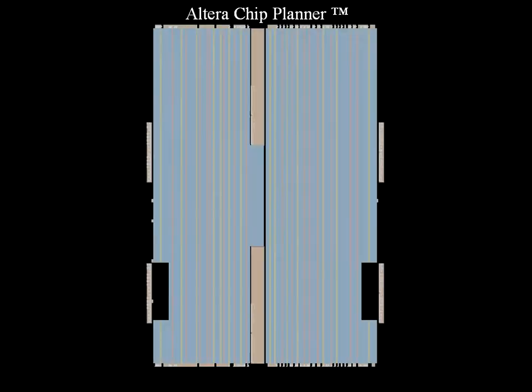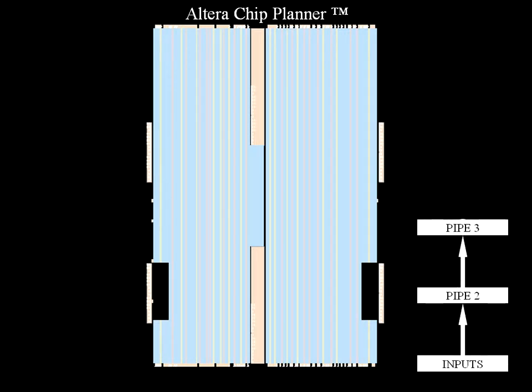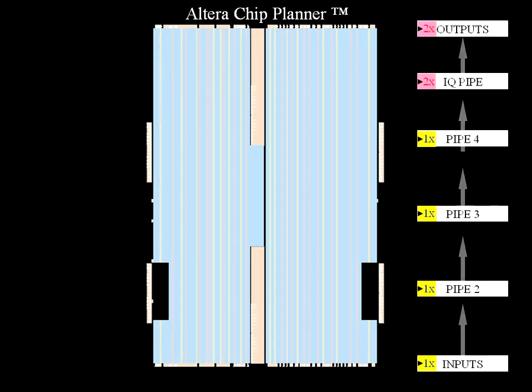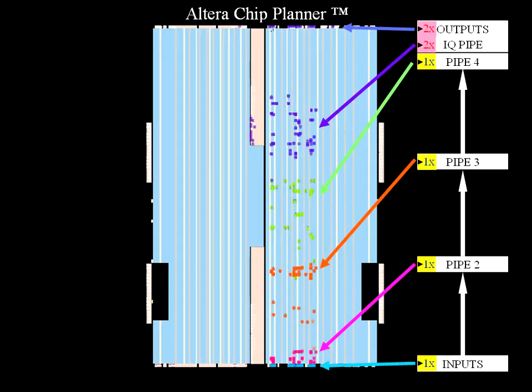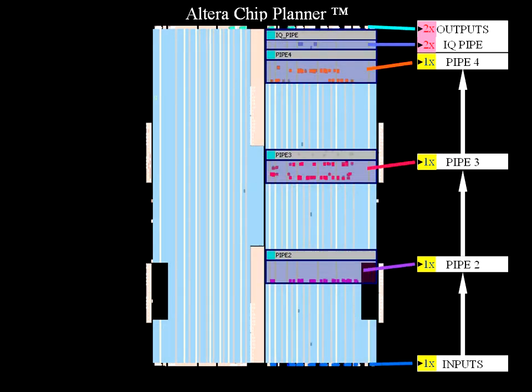Altera's chip planner allows placement of logic. Consider this 71K logic module device. Assume you wanted to configure it with a design pipelined across the chip. You might expect the pipelines to end up equidistantly spaced if all are clocked at the same frequency. But let's also say the last 2 stages are running twice as fast as the rest. Then you'd want the latter 2 stages to closely relocate accordingly. Here's a snapshot of the unconstrained placement. Pretty good, but not quite what we'd expect. Adding general region constraints improves pipe placement, and tightening up the regions improves placement even more.